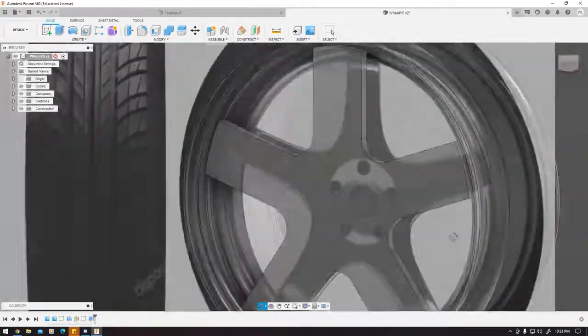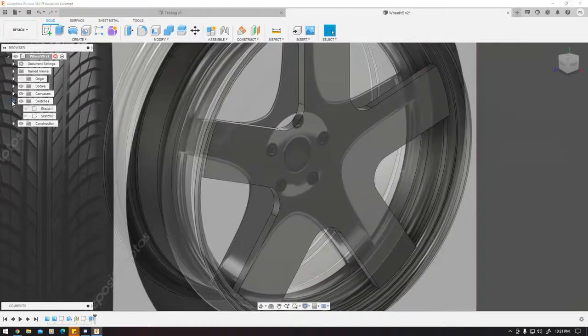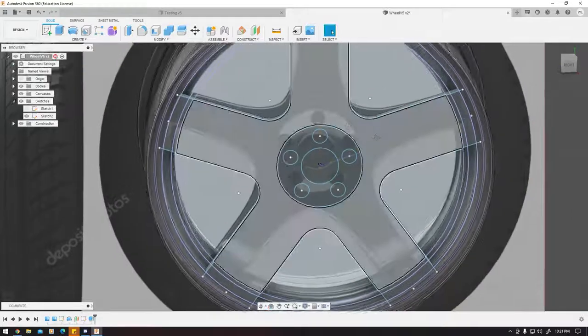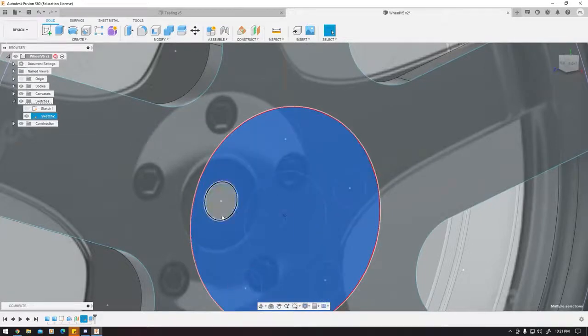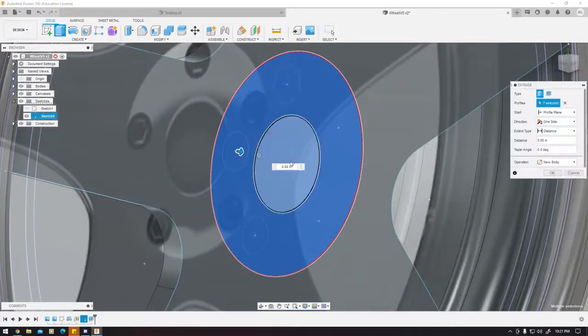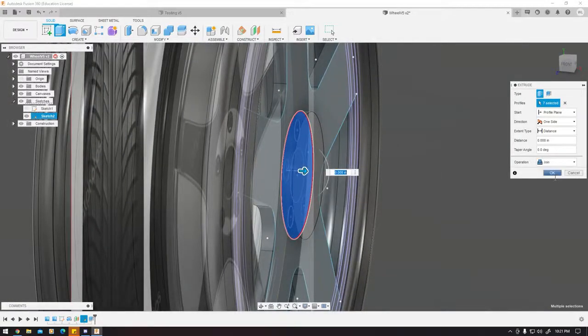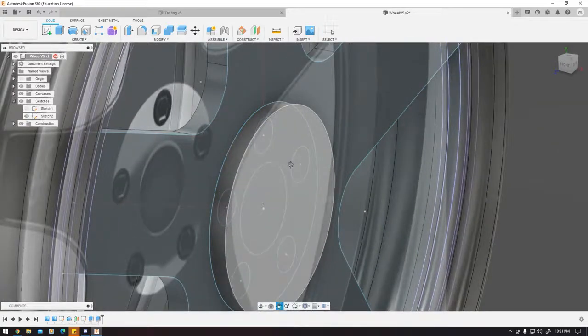We got our shape. Now we still need the inside information. So we're going to go into our sketch folder and show our second sketch. Now what I'm going to do is click on everything on the inside circles right here. Press E to extrude, and we're just going to extrude by 0.008. Press OK. It's going to automatically join since it's starting off from this surface.